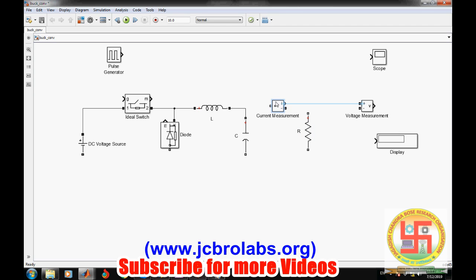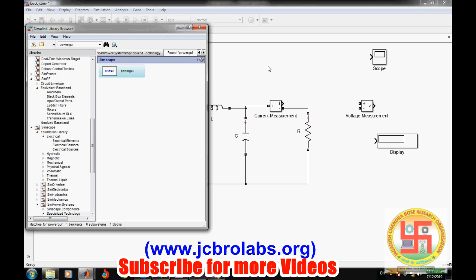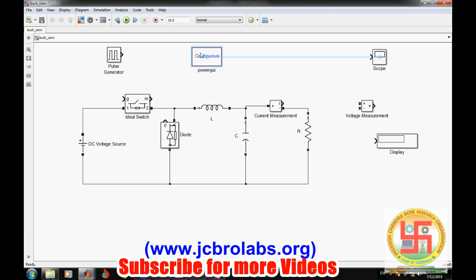Now we want a current measurement, so we will connect a current here, and the output of current will go here, and all these things will come together. One thing we forgot to add is the powergui. Without this, this model will not simulate. So we will put it in continuous mode only.